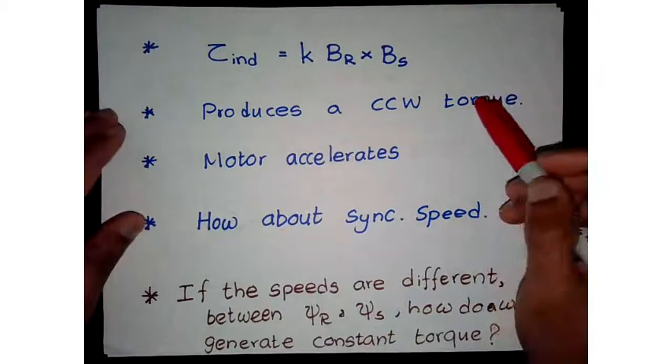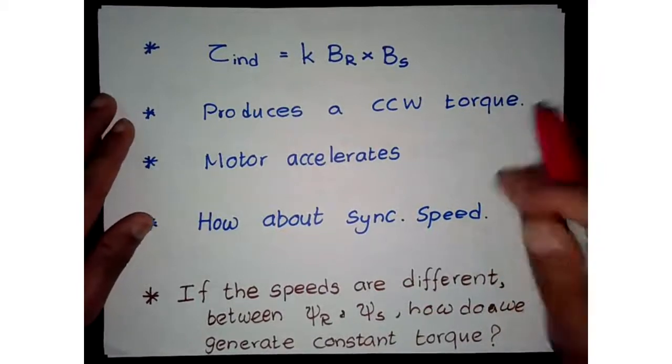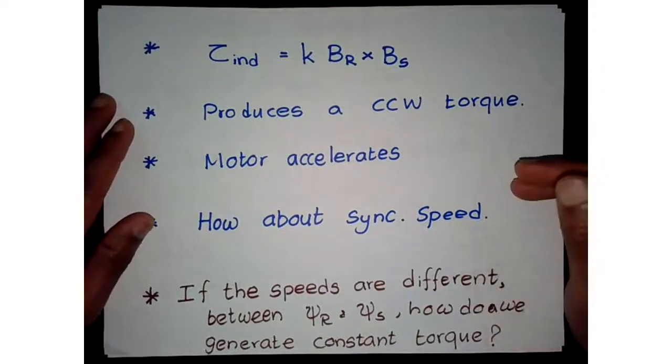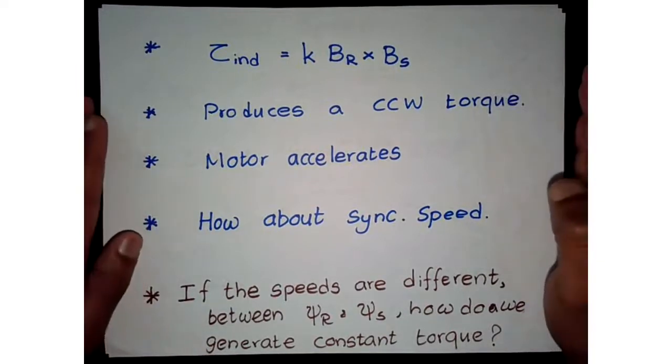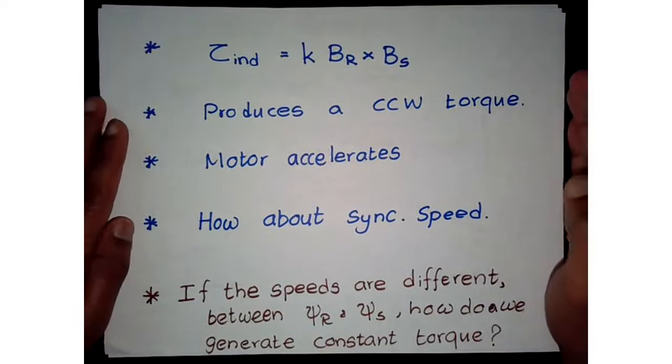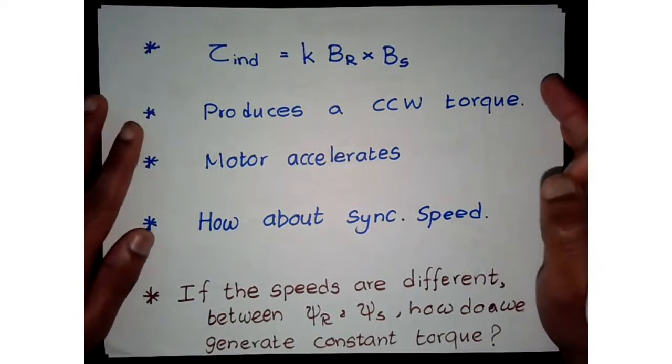But typically, what will happen is, since there are some losses, the friction, all that, it will operate close to the synchronous speed, but it will never reach synchronous speed. Okay, especially when you have some load.